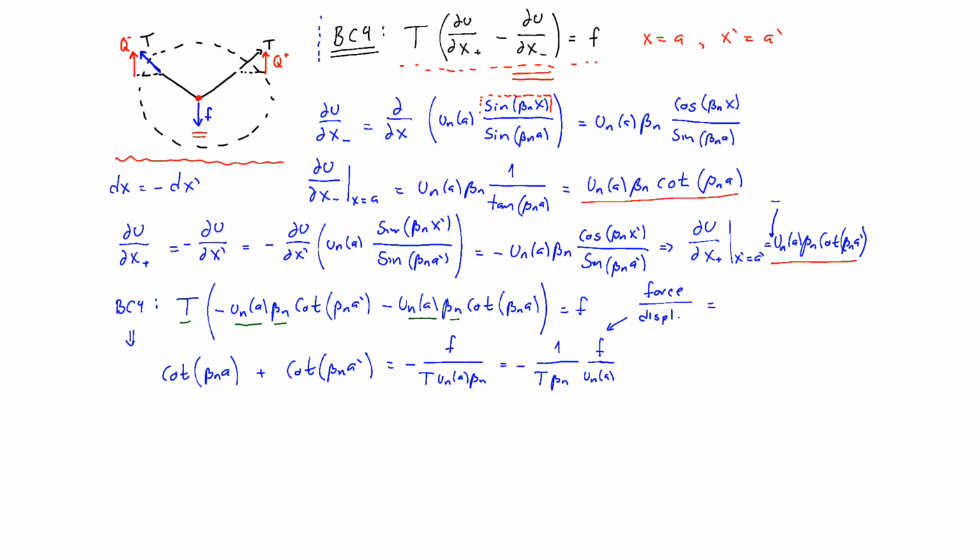And that's related to stiffness, or at least a complex stiffness, because we don't know what the mathematical model for the damper is. But what we will assume is that this f divided by u represents some kind of function, here referred to as capital H, which is a function of frequency omega, and it represents the transfer relation for the damper.